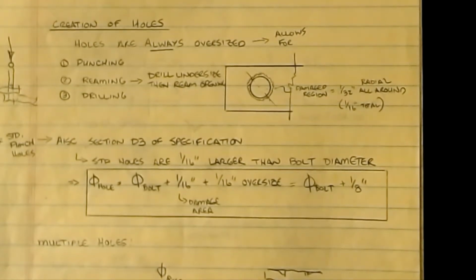Okay, whereas if you're welding, then you've got to have a way to hold the piece in place. There's got to be a certified welder on site and those kinds of things. So bolted holes are a lot more labor up front, but generally the construction of the structure itself occurs a whole lot faster. And that's one of the reasons that we like these drilled holes.